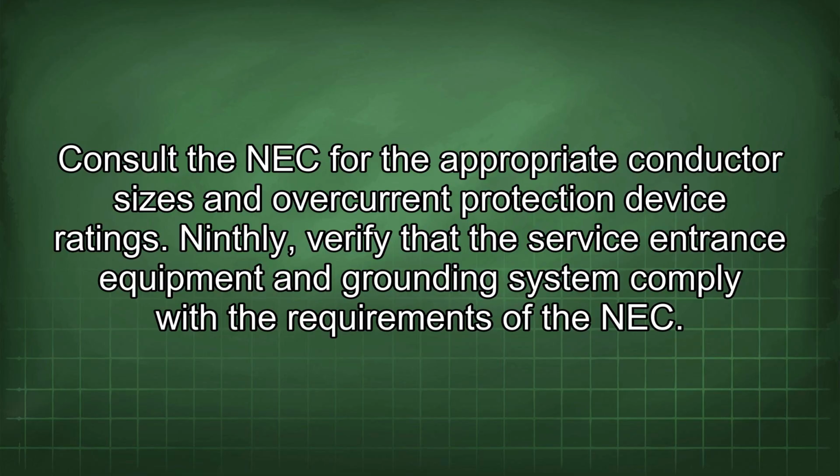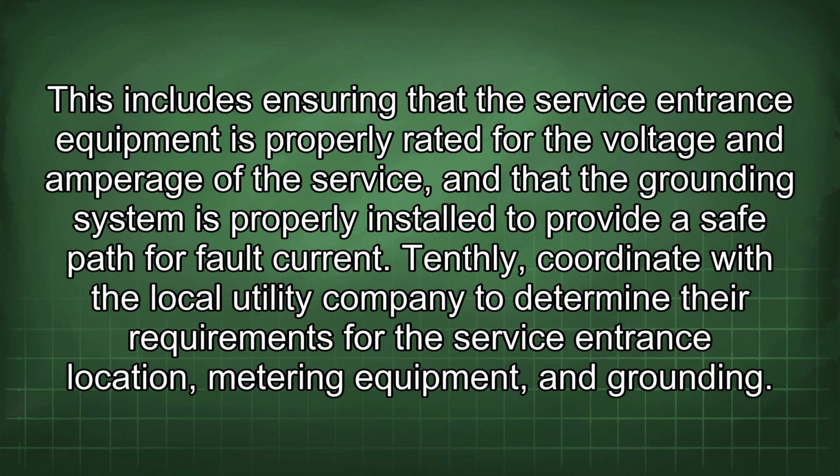Ninthly, verify that the service entrance equipment and grounding system comply with the requirements of the NEC. This includes ensuring that the service entrance equipment is properly rated for the voltage and amperage of the service, and that the grounding system is properly installed to provide a safe path for fault current.